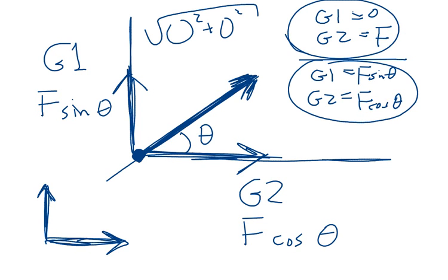I end up with that magnitude of force F. So just because I attach these force gauges in two different ways, I'm going to get two different sets of readings from those force gauges. But even though those two sets of readings are different, they represent that same force. So it's the same thing when it comes to stresses. When I have this rod under tension, it makes sense to set up my coordinate axes such that the square is just lined up with the direction of the force, and then all I have is a normal stress. There are no shear stresses.